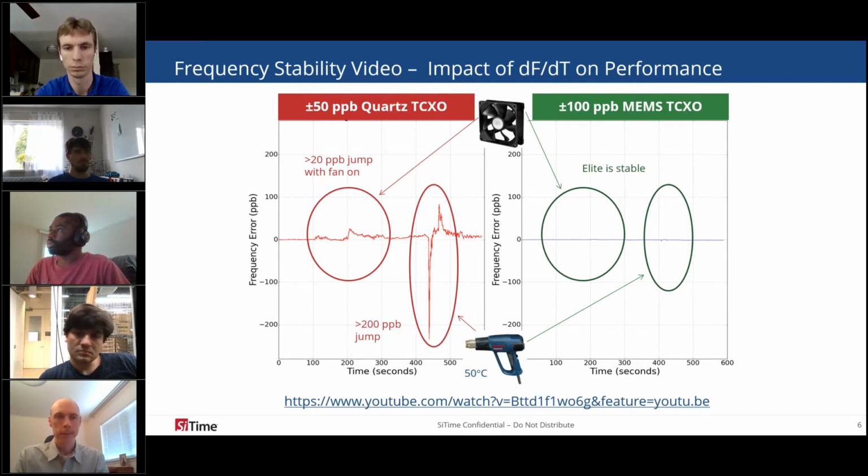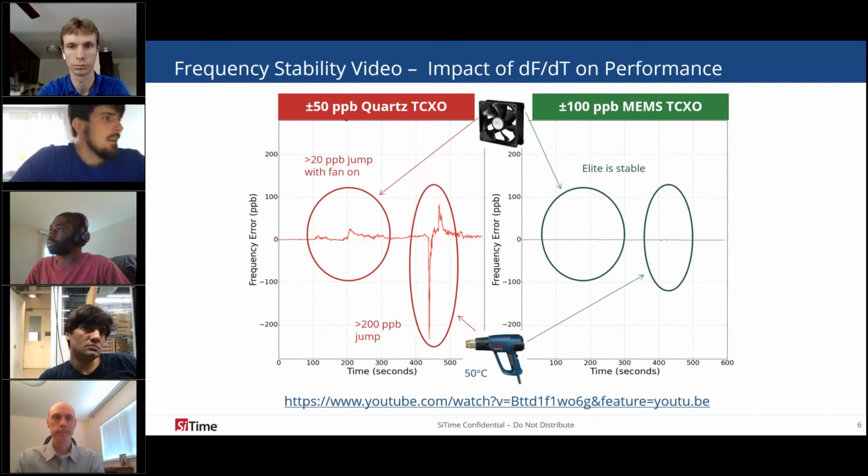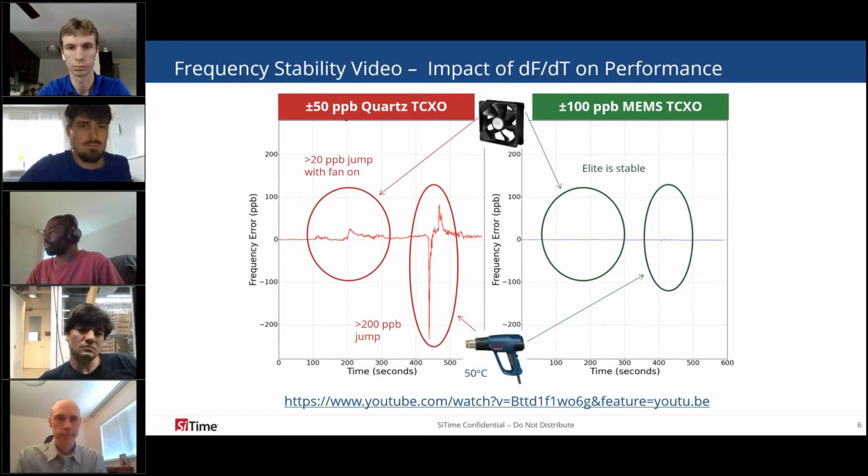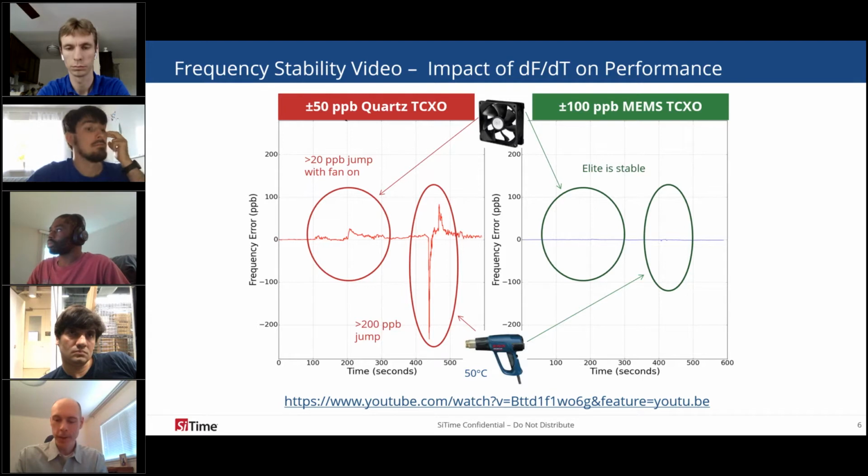And by the way, oscillators do respond to acoustic noise as well. I have seen often controlled oscillators that were affected by just the noise created by a fan. Yeah, vibration can also have an impact, although I'm not talking about it specifically here, but yes, vibration as well. Yeah, we've seen cases where people have a rack with a baffle in the front, and that'll impact the way that the temperature flows through the rest of the chassis and create kind of strange effects.